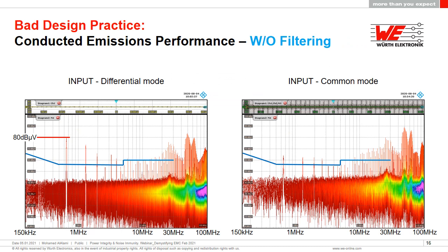And this is also another interesting result. So the previous results that we have seen were using the ESRP EMI receiver. What we've decided also to do is use that RTO oscilloscope, and it's got a very nice function called a spectrogram function.